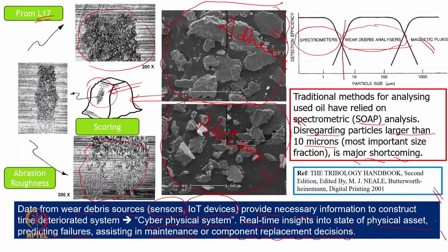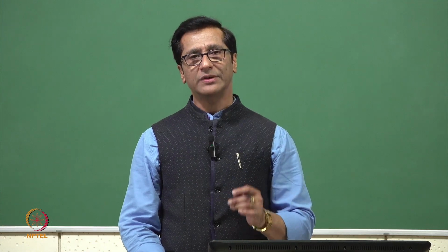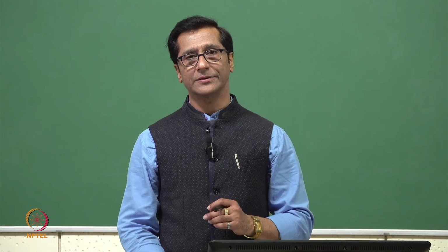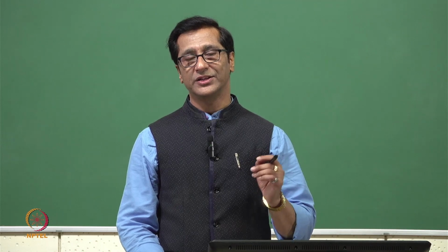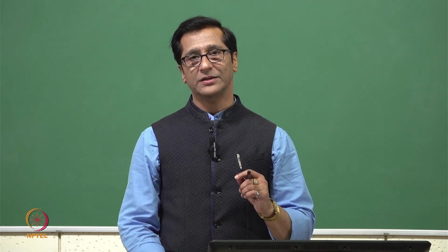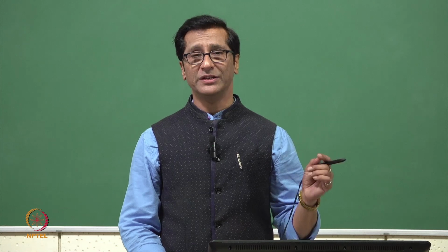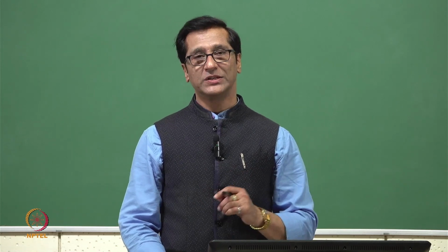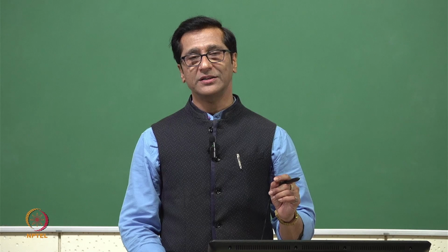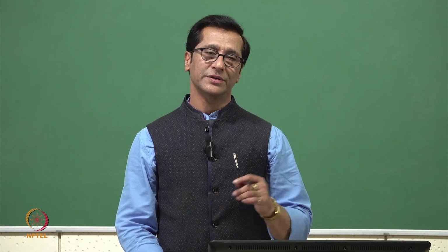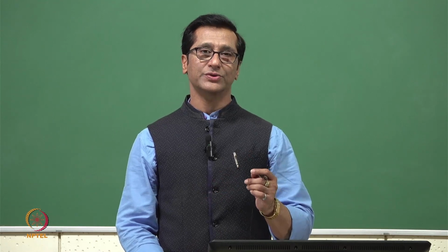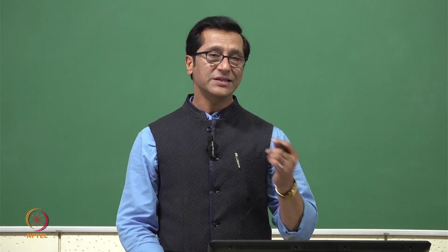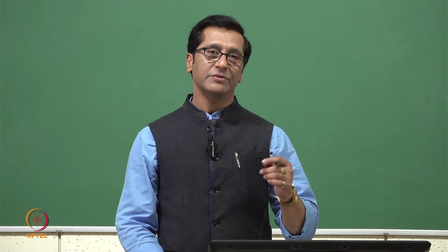I believe that wear debris is really going to give a lot of information, and that will be helpful to build the cyber physical system, and that will be really useful to delay the degradation. As in the beginning of the course I said that wear cannot be eliminated, but it can be delayed. So instead of the operation 10 hours, we can make it 100 hours. Instead of 1000 hours, we can make it 10,000 hours.